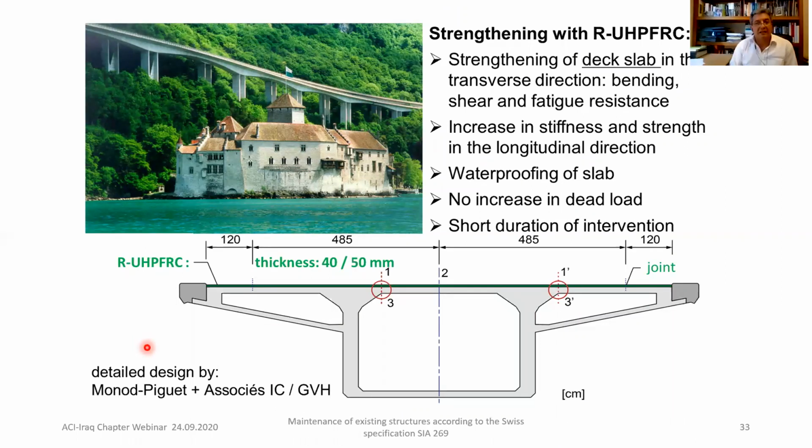He used reinforced ultra high performance concrete, and he just added 40 to 50 millimeters, 5 centimeters, over the deck to reinforce it first and to protect it from fire, waterproofing, and all necessary reinforcement as a structure part. So Professor Breuwiler, this material is actually, I think, a new material, and he was one of the pioneers in this domain.